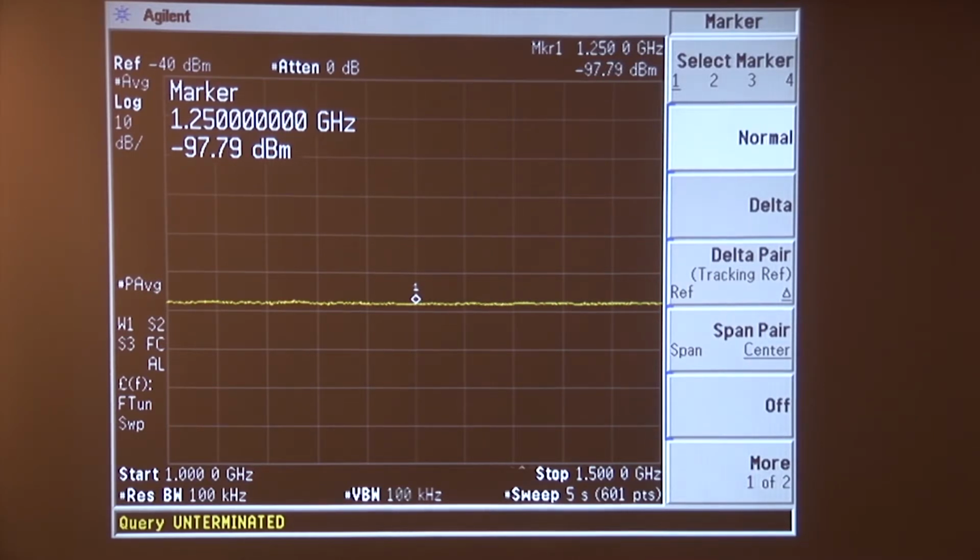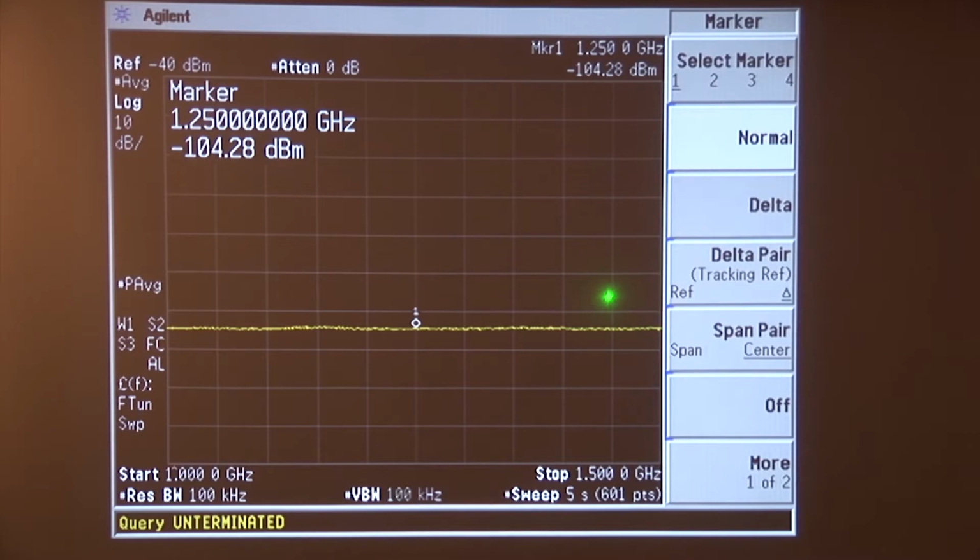You can do it with a pocket calculator, and if this on versus off ratio that we see here were to get to be 10 dB or larger, remember that you could just take that difference and subtract it from the ENR of the noise diode, in this case 25, and you'd have the noise figure directly. For example, if you turn this on and off and you saw a 20 dB difference between on and off, and you subtracted that from the 25 dB ENR of the noise diode, you could say, okay, this thing has a 5 dB noise figure, and if you actually do the math, you'll find that it's within a fraction of a dB of 5 dB. Okay, now, having done that manually, any questions about that part of it?